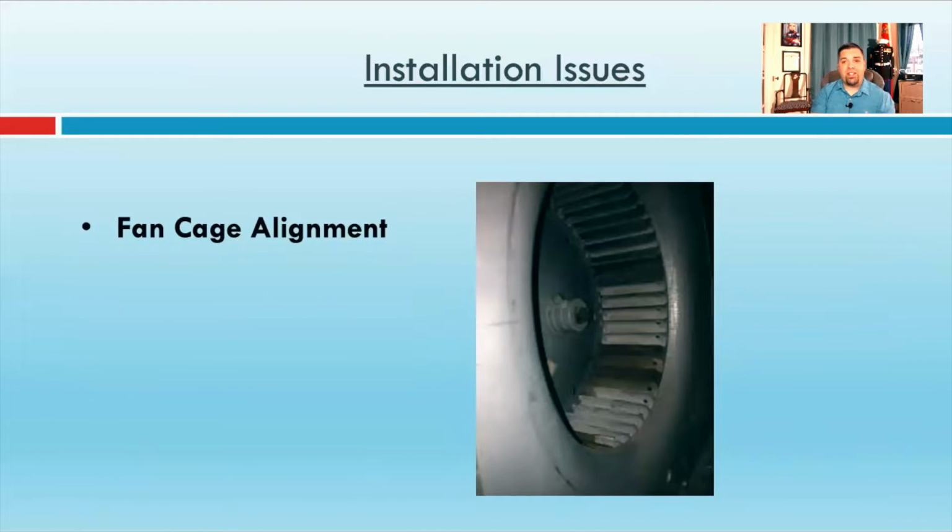And then some of the basics, especially if you're going to go back and test and balance an existing system or recommission a system: you have to make sure that the fan cage alignment is correct in the blower section. This sounds elementary, but it's unbelievable out there. As soon as some of these become imbalanced, the most amazing things happen, okay? Or if somebody replaced the blower, maybe it's not the right horsepower, who knows? Maybe that cage is slightly off. That is obviously going to impact total volume of air.